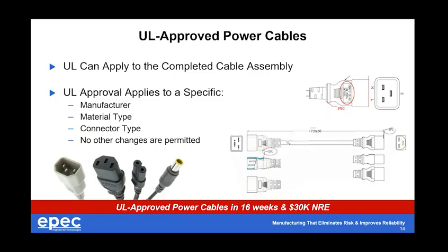But just as we said how these requirements all fit within various UL specs for material, connector type, and such, if you or your end customer wants to change one of these things, like for example, if we're using a service cord that's traditionally made of TPE, and because of the application, you're trying to use this in a setting where you must use a TPU or another thermoplastic, we cannot certify to UL without actually going and performing those third-party tests. Some of these can take a few months and cost tens of thousands of dollars, depending on what's involved.